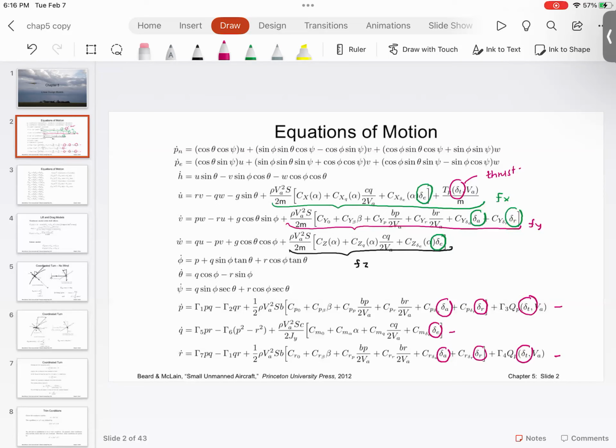So what we are going to do is take these super complicated nonlinear equations of motion, approximate these equations into some linear form, and use those linear functions to control our dummy aircraft. And believe it or not, this technique works quite well. As a matter of fact, even if you have a complicated equation, even if you have a complicated aircraft, you will notice that in the majority of the flight regimen, the final equations assume this linearized form.